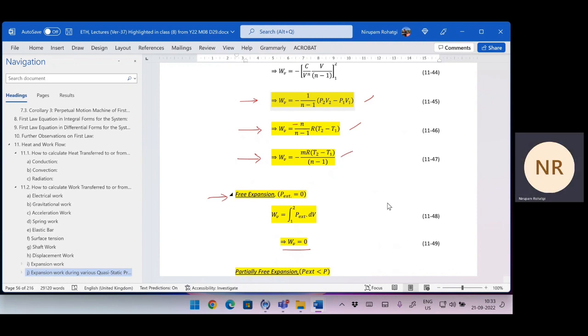Actually, these are more of a theoretical nature because on a closed system we do not do much practical work. Because all machines are open machines, open flow machines, or open systems. So actual problems come from the steady flow energy equation, not from this. This is just to understand the whole thing.